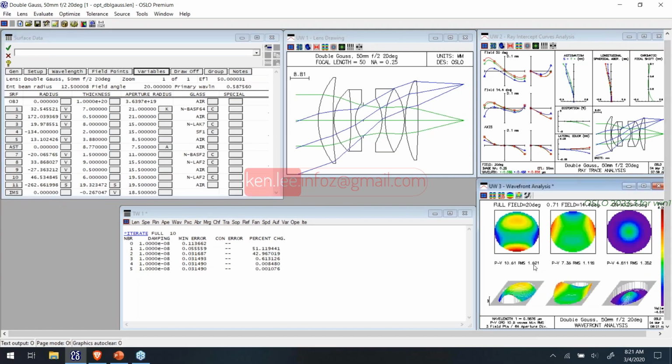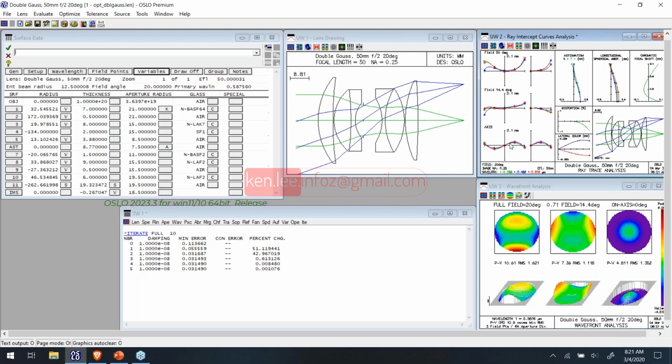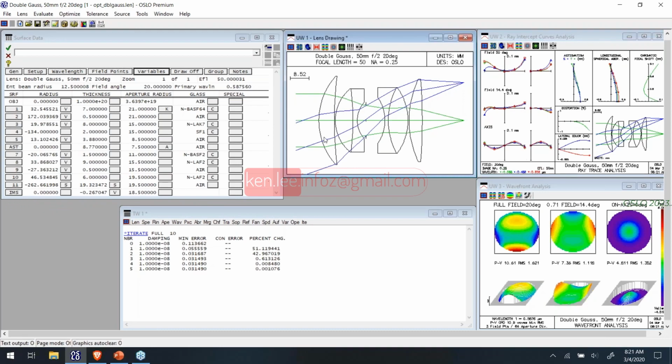And our RMS wavefront errors, I don't know if they were something like 3, and now they've dropped down to 1.6. So pay careful attention to the ray fans here, and you can see that it's in better focus and has been improved. I could have also just typed UDA and updated all of them. So one way you might want to operate is you keep 2 windows open. You have your metrics you're looking at in one, you do your optimization, so you only update one of the two windows so you can compare the two side by side. Easily functional to do that, maybe a little different than some other programs where you put a freeze on a window or something like that.